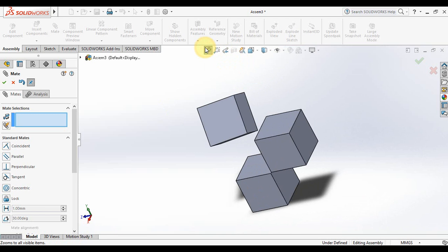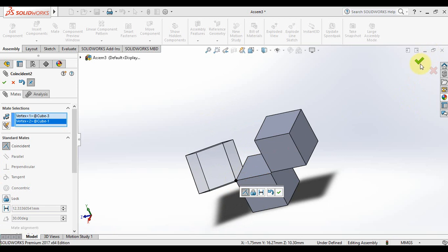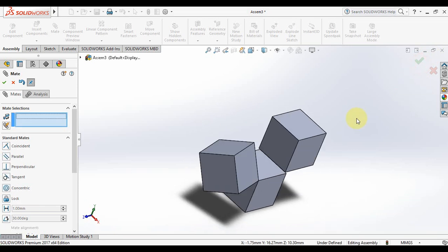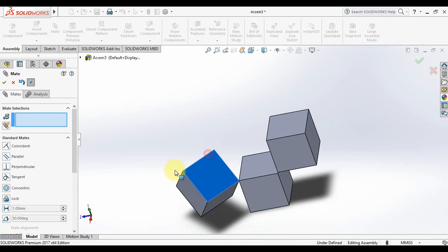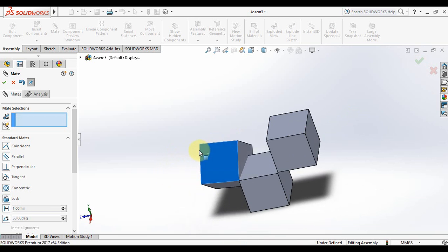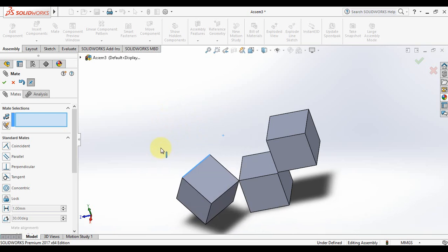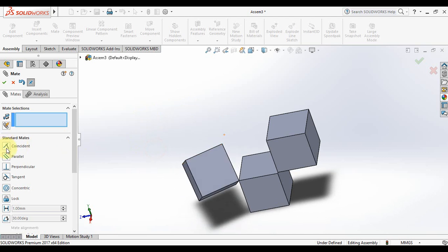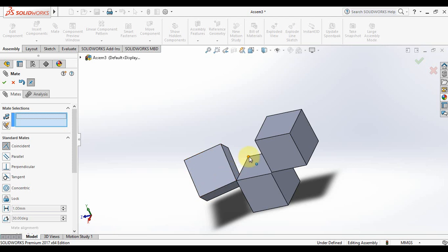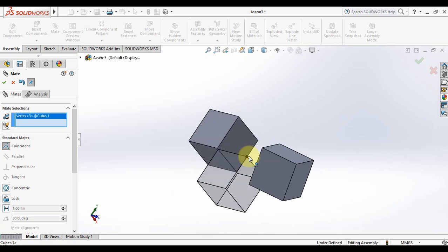So next step, I'm gonna make it coincident. I can use, for example, this dot that is right in the corner, and this dot that is right on the corner. So now the dot is there and the two surfaces that we selected are perpendicular. But remember that this is a thing in 3D, not in 2D. So it can be perpendicular mostly anywhere. So how can I fix that? Again, I'm going to select Coincident, and I'm going to make Coincident this corner and this corner.